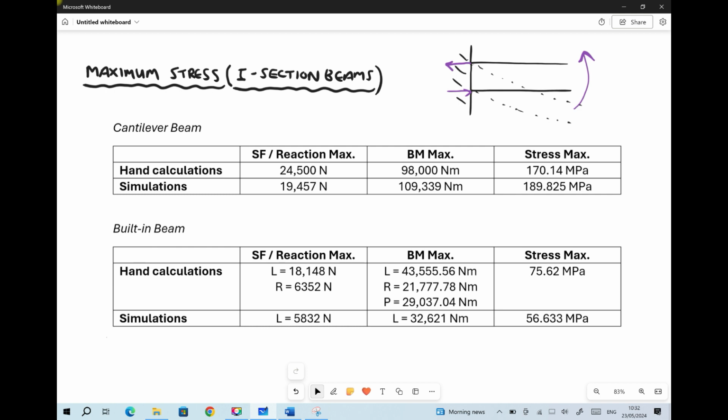Now that turning moment is also going to have an impact on the reaction forces. If we consider what's happening at the other end of the beam, then we're going to have exactly the same effect, where we have tension at the top surface of the beam and compression at the bottom surface of the beam. So we're going to see an opposing turning moment acting at our left-hand support as a result of the forces at the right-hand support. So we can see that there's lots of things at play here, and there's lots of things affecting the support reaction. From our simulations, what we determined was the total support reaction at the left-hand side, rather than the vertical support reaction, or the support reaction acting directly upwards.